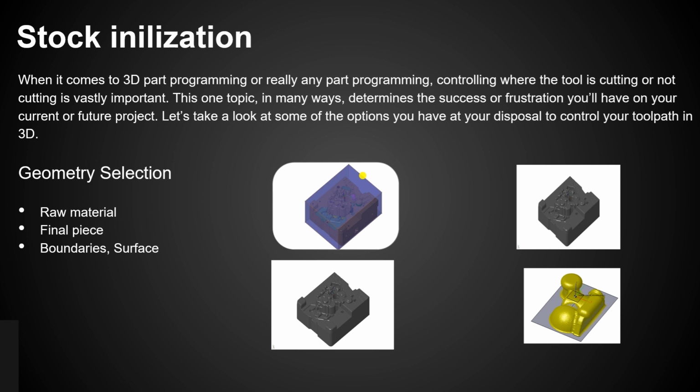As you see in this picture, I mentioned here 10 mm stock, here 5 mm, or here 3 mm. So it will run only those particular areas. Suppose in a forging unit, if your die is worn, then what the forging man does is cut 10 to 8 of the material according to its wear. They cut all the material on a conventional machine because the inserts are costly, so they do not cut it on your VMC.